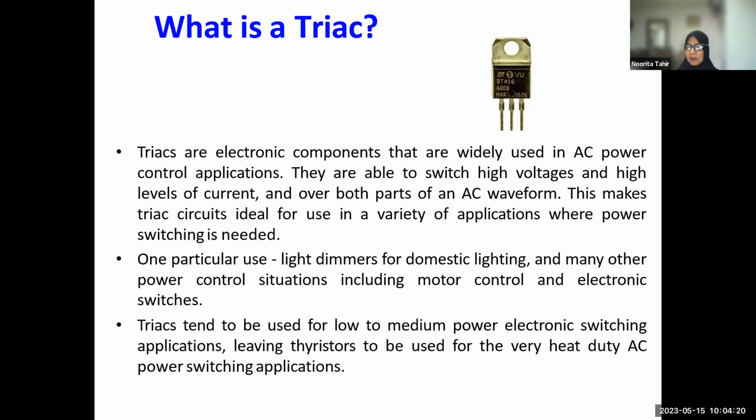So for a basic thyristor circuit, only half of the waveform is used, and that means the basic circuit using thyristor will not utilize the whole AC cycle. So 2 devices like what has been built and known as triac is required for both halves of the AC.